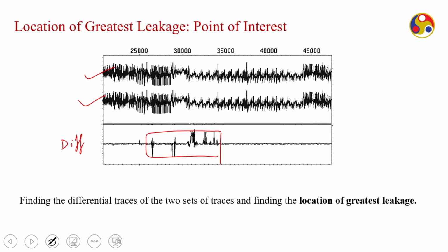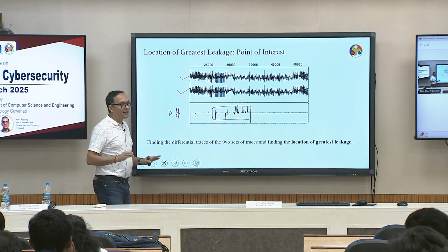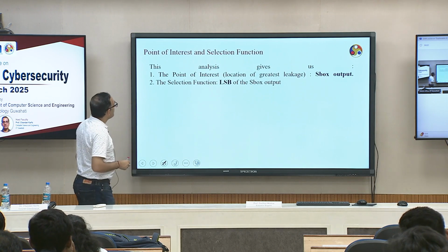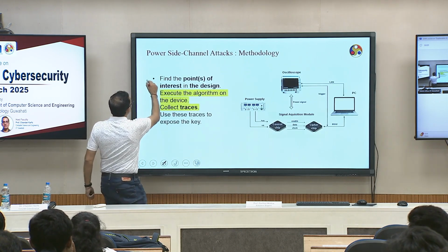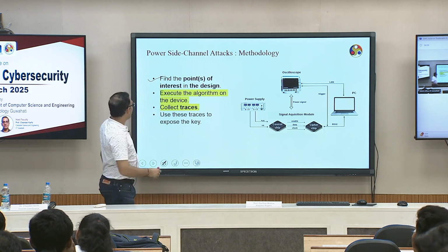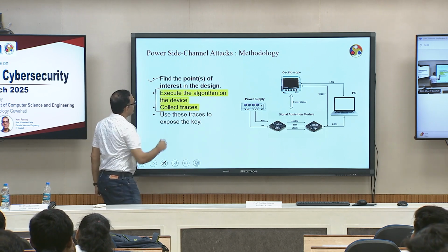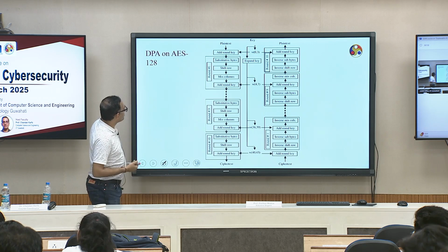So, I have done my homework, I did some experiments, I figured out which bit to track, which operation to track, and how to track. So, everything is done, now I have to do the actual attack. Okay. So, now I have already found the points of interest in my design. I will now execute the algorithm and collect the trace. That is something I am going to do, and let us see what I am going to do.